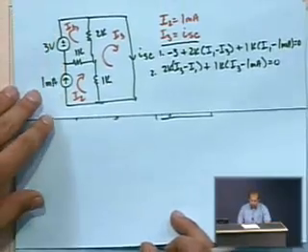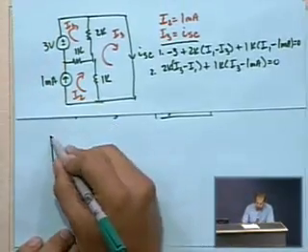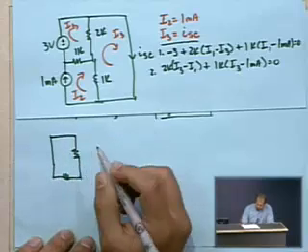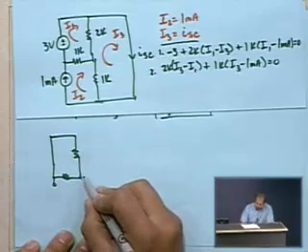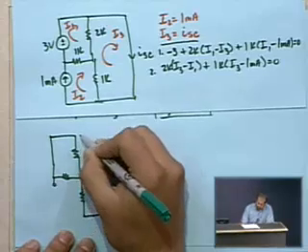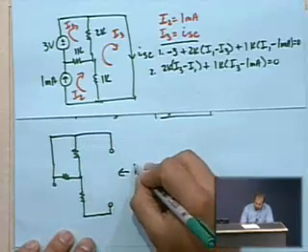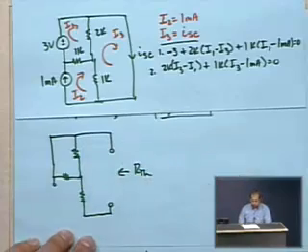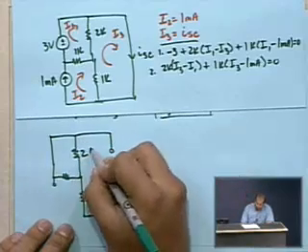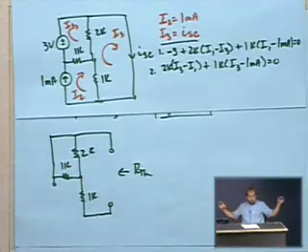So we short circuit the voltage source, so there's just a short there. You've got the 2K resistor here, the 1K resistor here. This is opened up. We've got the 1K resistor here. And then we look at that all from the terminals of the load. So what is the Thevenin resistance looking in from those terminals? So we've got 2K, 1K, and 1K. So what do we have there?